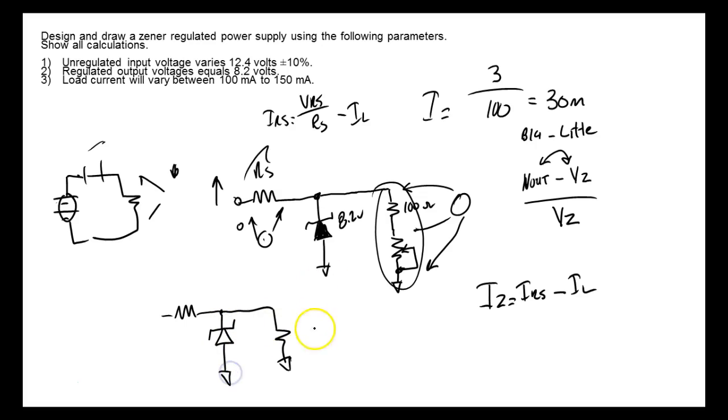and we operate it. So let's say this guy right here, it's rated at 5 volts and it'll burn up if it ever sees anything over 7 volts. Well, I'd use a 7-volt Zener right there. And what would happen? Well, if it tried to get up above 7 volts, what would the Zener do? It'd just clip it off. Right? You understand that? It'd just clip it off. So we use them for all types of things.